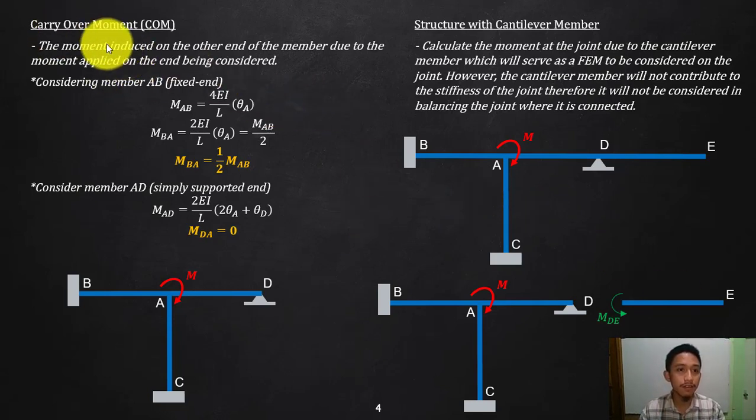So what is carryover? That is the moment induced on the other end of the member due to the moment applied on the end being considered.